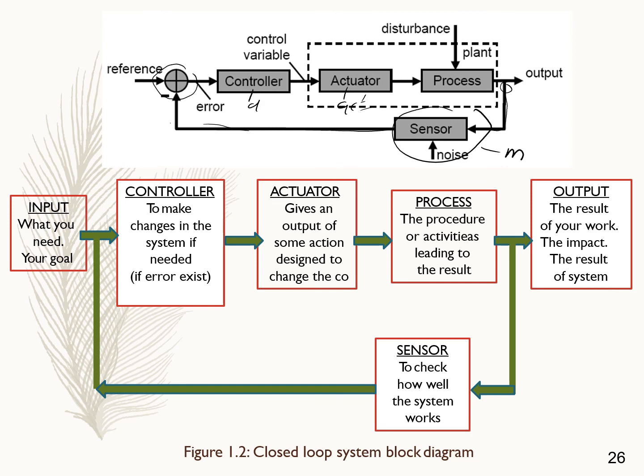Like what I was saying before, we have input here, and we have controller, actuator, process, output and also sensor. From here, for example, we need the temperature here to be 100 degrees Celsius just now. T desired, our set point, is 100 degrees Celsius, and then the sensor will read whether the temperature going out from the process achieves 100 degrees Celsius or not.